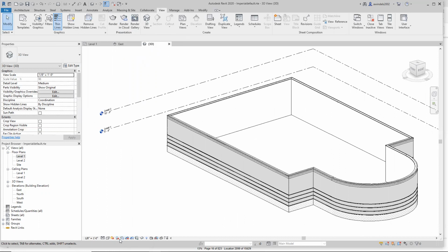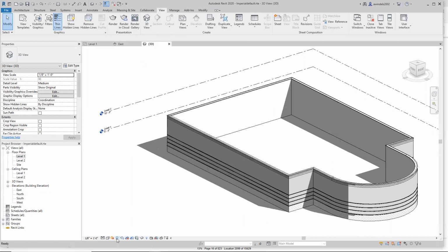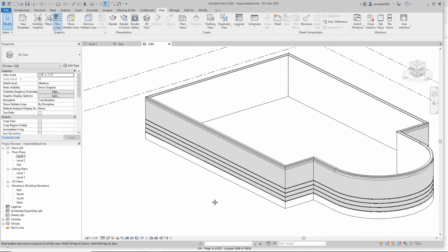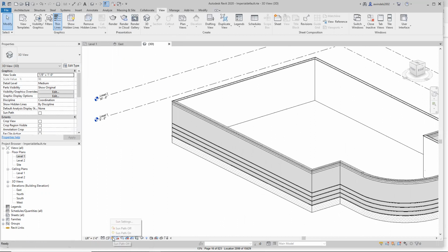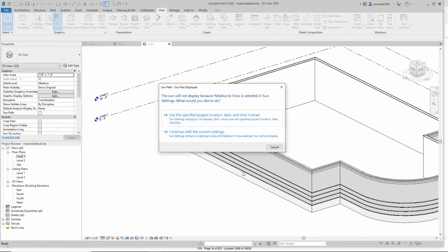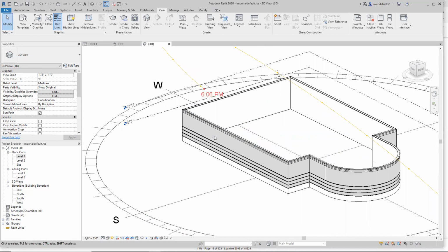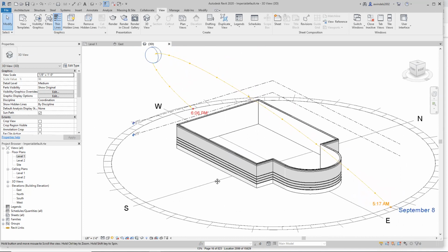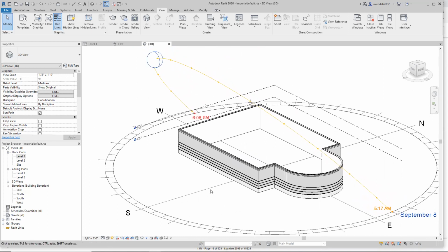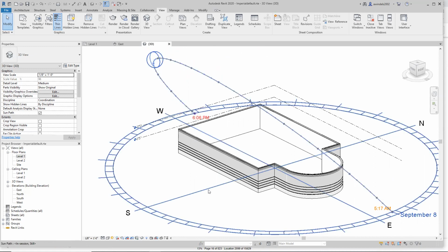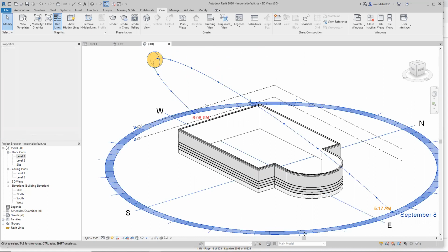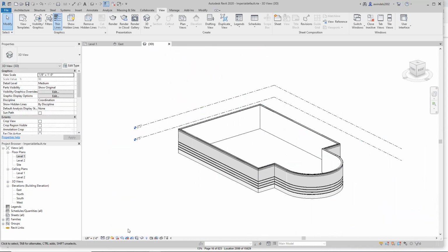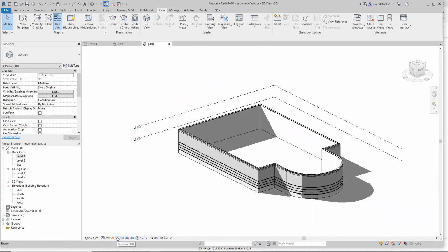I'm going to turn on and off some shadows. Turn them on here, off, on. Wouldn't really do a lot in a front view. Turn the sun path on. That says where the sun's going to hit in a certain location. So you can study your solar gain in a building, where it rises certain times of the year predominantly, right? That could be really big. You orientate your building about this. I'm going to turn this off for now. Turn the shadows back on for fun.